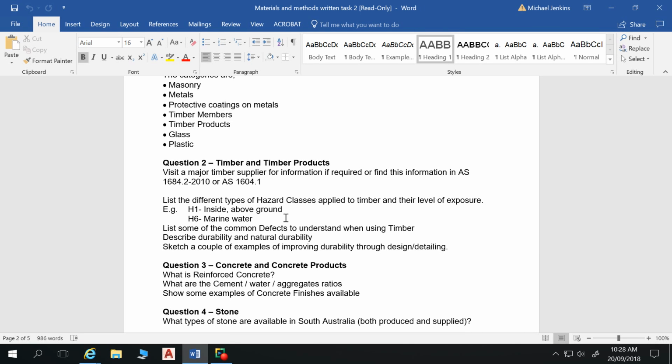So a very common detail that you'll see is a sloping end cut of the timber as well. That enables water to come along here and run along that face, and then get a bit of speed up and drop off rather than gathering in there.